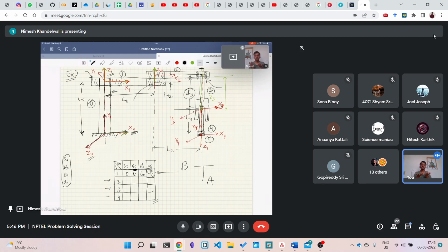We are using different conventions. So the DH convention is a way of standardizing how you calculate your transformation matrices, such that if you have written these parameters correctly, your transformation matrix will always be the same.